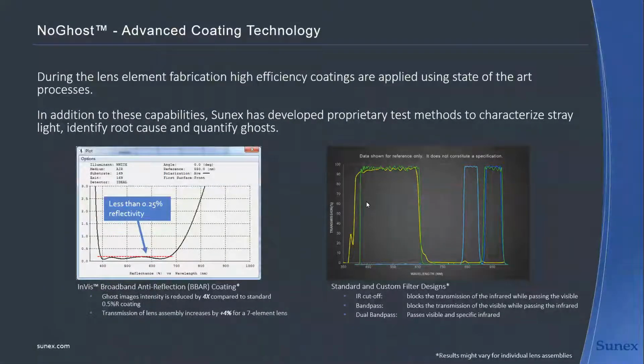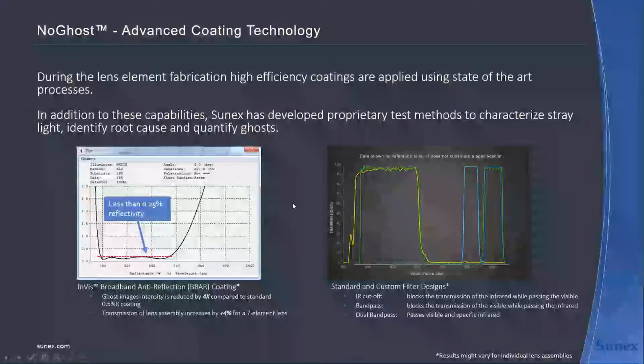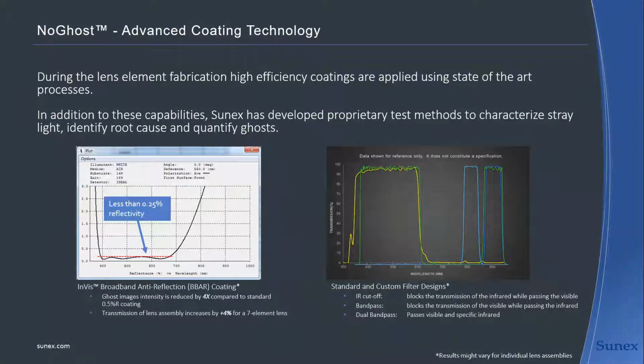Yeah, and like we talked about before, use case is extremely important. Things like what kind of light source, is it mixed? When I say mixed, I mean visible plus infrared, or is it going to be one or the other at any given time? What kind of filters do you want? Are they switching filters? Are they passive filters like what we're showing here? What kind of things are you looking for? Is it going to be a fast exposure? Is there motion, or can you tolerate a longer exposure time?